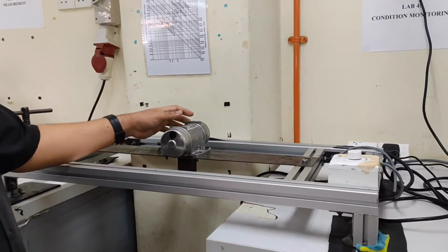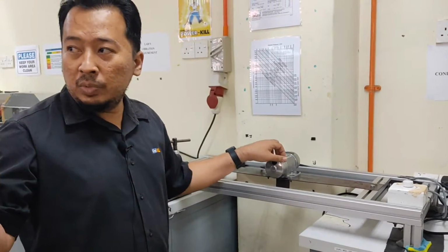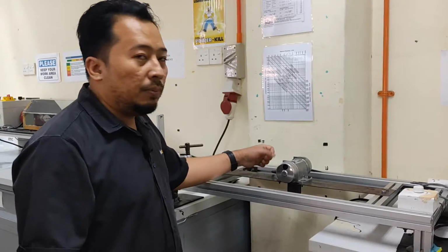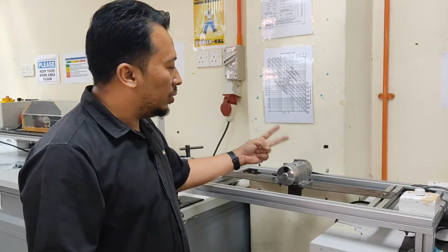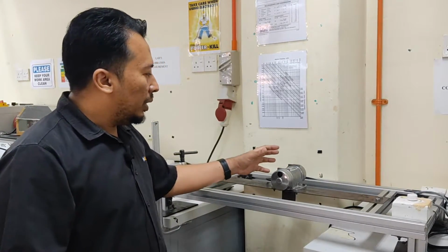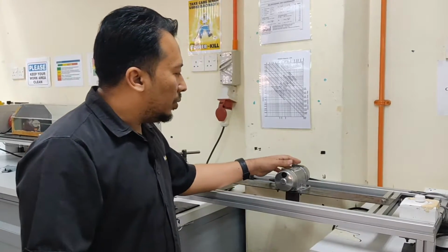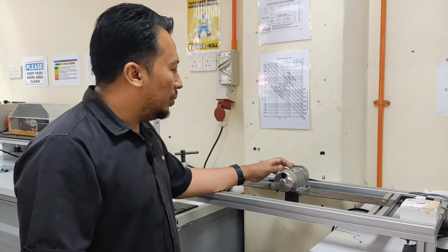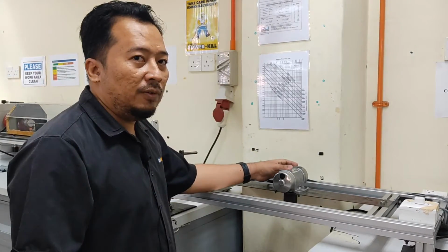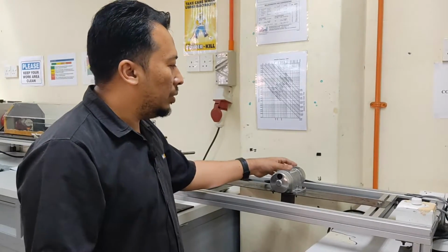The determination of the natural frequency can be done using the experimental modal analysis of LMS, or students can also do it using the bump test. So there are two methods to determine the natural frequency. Students need to decide which method they will use, and also suggest how to reduce the vibration after they determine the natural frequency. They need to suggest a method to reduce the vibration and test whether it is successful or not in reducing the vibration level.